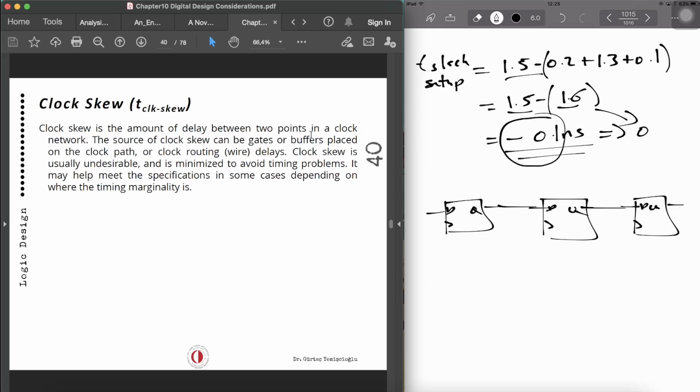But the problem was, if you are using the same clock for all of those, it might be a problem that they're switching at the same time. So sometimes, in order to not do that, we can introduce, as you do remember, an inverter so that one of them is switching, the other one is waiting.